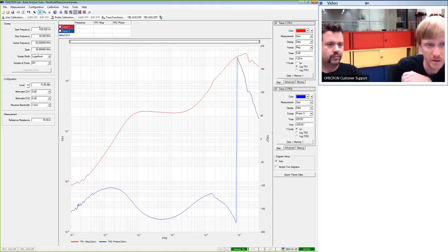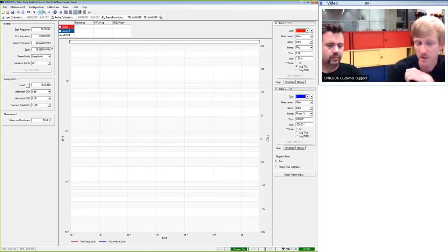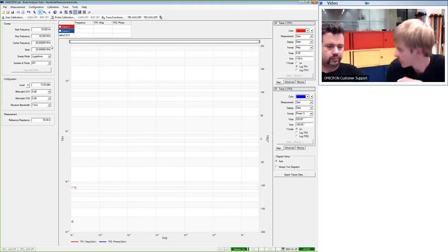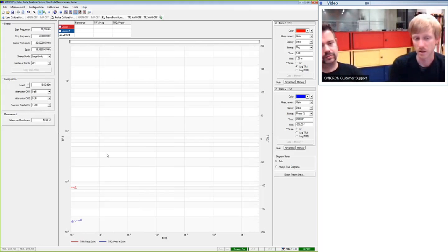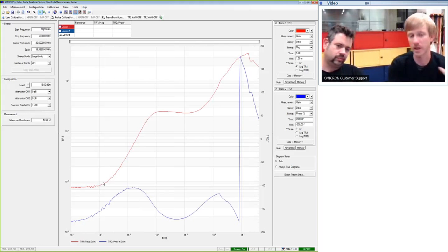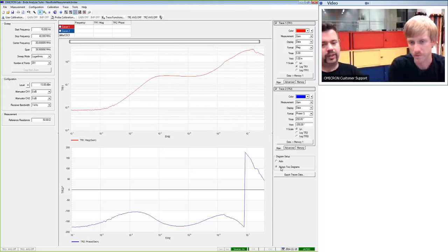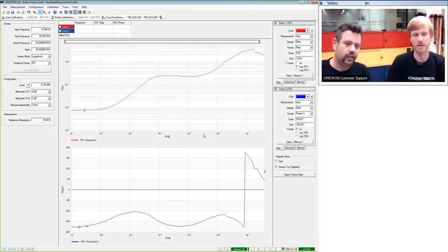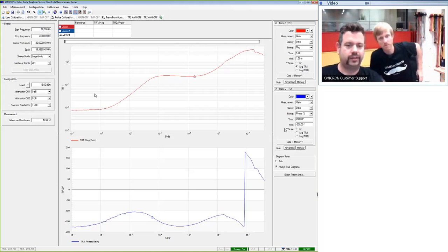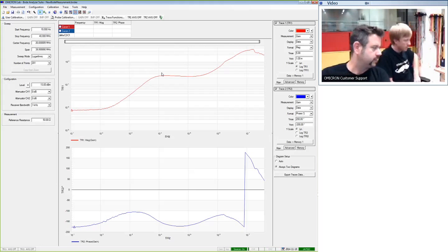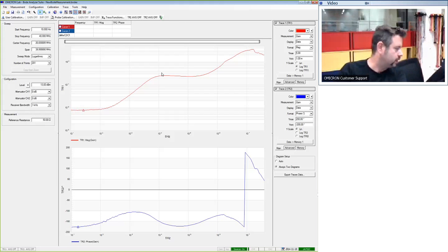What I will do in addition is set the start frequency to 10 Hz such that we see the area where the regulator is really not looking like an inductor, but like a resistor. I think in this measurement we already see that there is no real peak in the output impedance. I think we have activated the electrolytic capacitor.